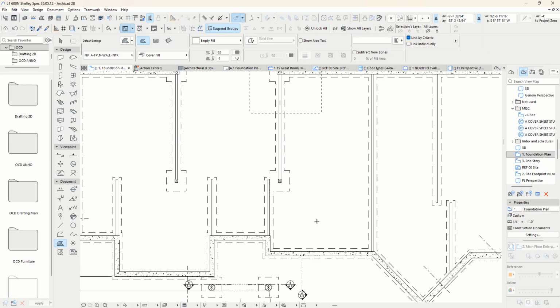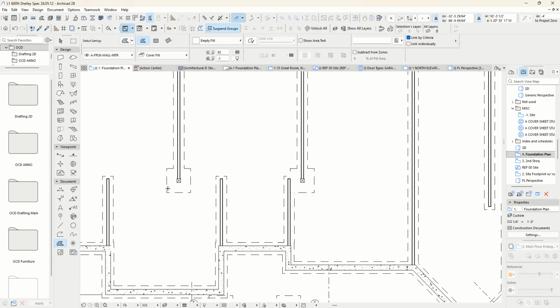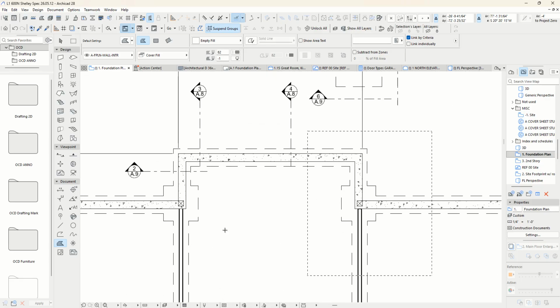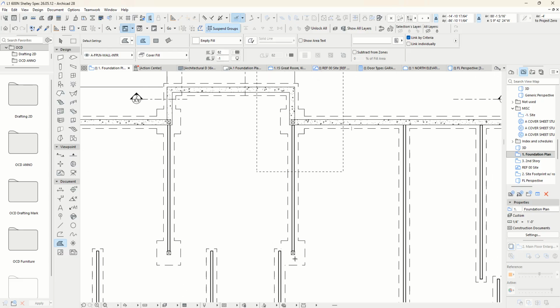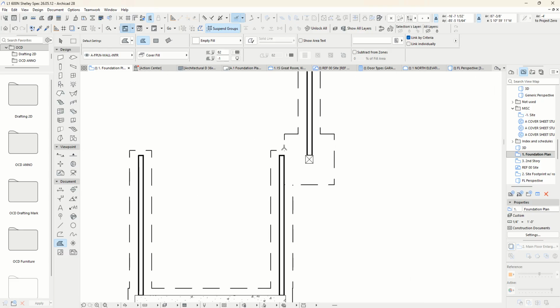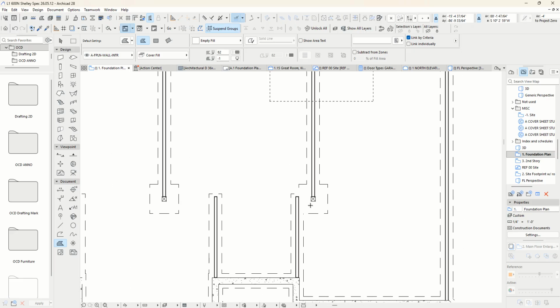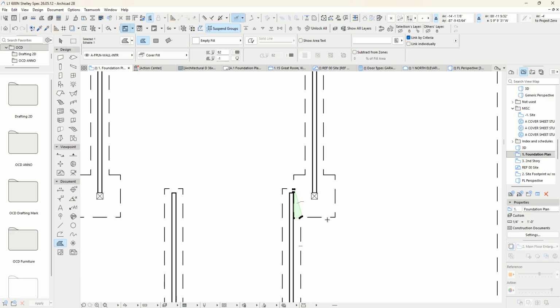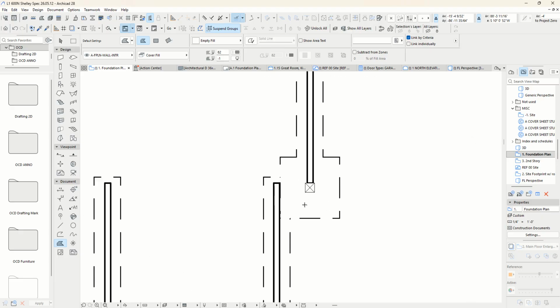Knowing these little tips and tricks can make things easy. And this is something if you're working for someone and they really want these things to look clean, now you know how to at least clean that up without ruining the integrity of your beams, by adjusting just the trim order, and you also know the quick fix on how to get this stuff done in an easy fashion. And I suppose you could probably use a mask, which is probably a lot bigger workaround, and a lot of people don't like those.